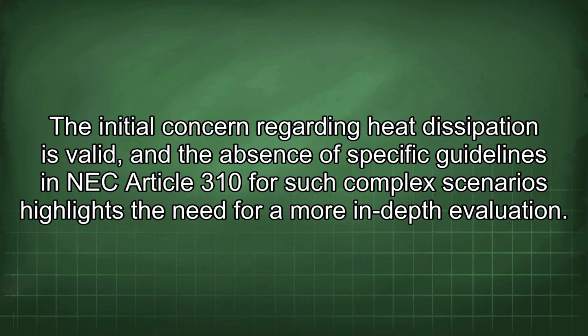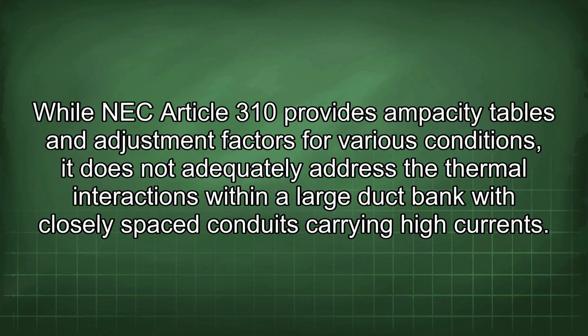The initial concern regarding heat dissipation is valid, and the absence of specific guidelines in NEC Article 310 for such complex scenarios highlights the need for a more in-depth evaluation. While NEC Article 310 provides ampacity tables and adjustment factors for various conditions, it does not adequately address the thermal interactions within a large duct bank with closely spaced conduits carrying high currents.